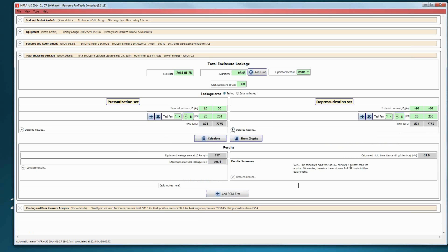So we'll just get rid of those detailed results. This is the door fan data that we entered: the building pressure and the fan pressure. Typically these will be 50.1, 50.2, 52, 53, that kind of thing. Usually you'll put that on time averaging and enter those.